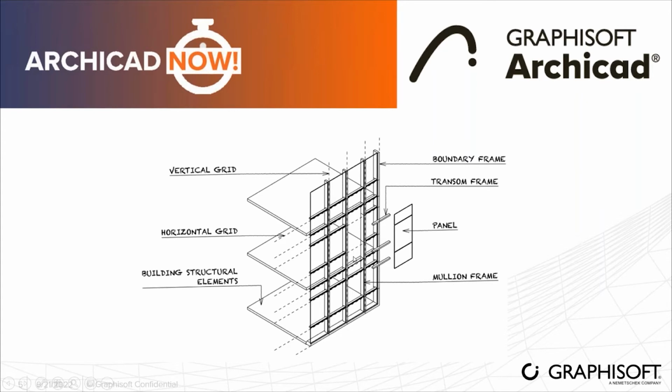To cover the frames, we have panels here. Apart from that, we also have boundary frames. You can see here on the boundaries on the sides and on the bottom, we have boundary frames. And apart from the ones shown here, we also have corner frames, which are not shown here. Whenever there is a turn in the curtain wall, we will have corner frames. You can see the building structural elements shown here, which are the slabs, just to show how the curtain walls are placed with respect to the other components of the building.